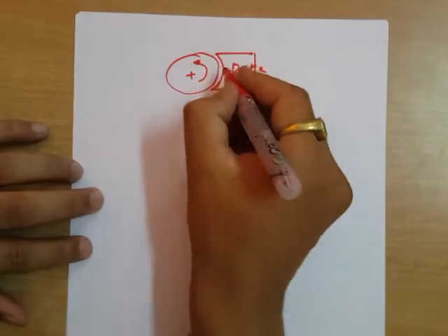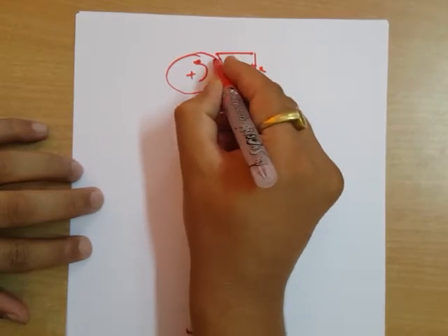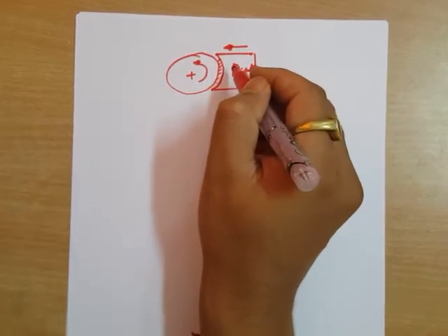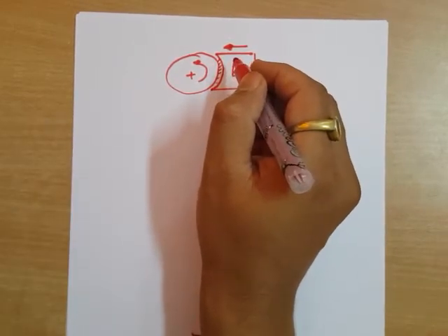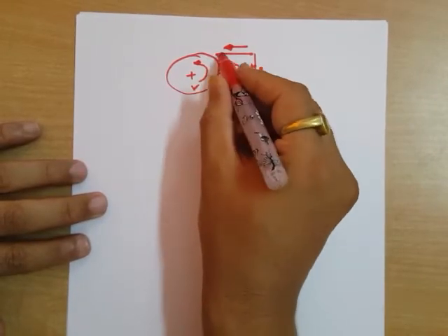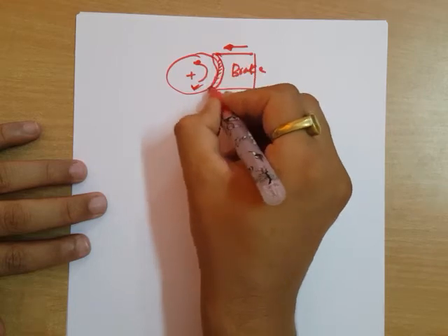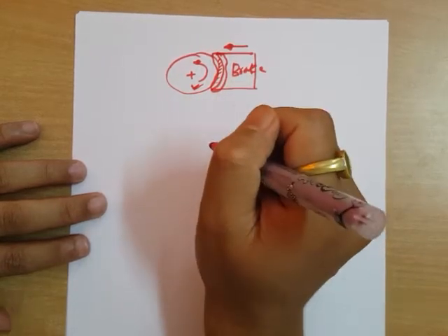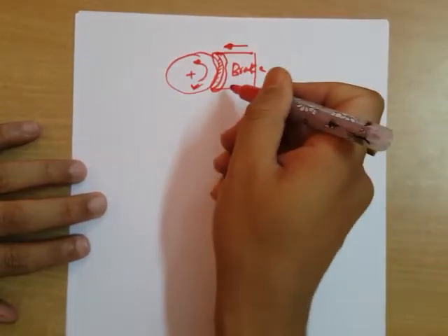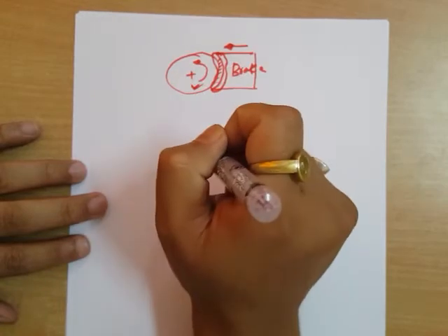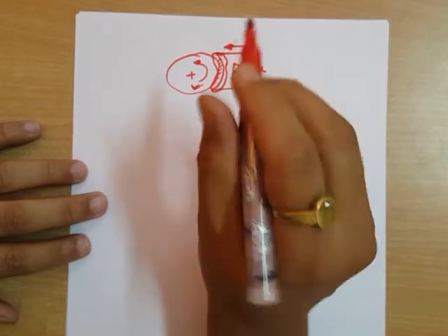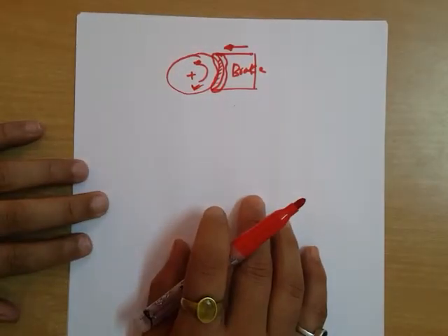So friends, if you neglect this space, or say that this space is very small when this brake is moving in this direction, so that no work can be done in terms of displacement, then the whole of the kinetic energy of this wheel will get converted into internal energy of this brake. And the reverse of this is not possible. If you supply heat to this brake, this wheel will not start rotating. So this is an irreversible process. But how to prove that this is an irreversible process? Let us say that this is a reversible process.